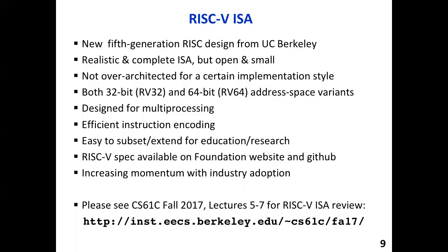In fact, if we wanted something like RISC-V, not only would we find the full-blown VHDL available, which is cool, but we'd even find compilers that support it, which is really important if you want to start writing programs in C and having them actually compile to this RISC-V processor. Because once you got that, now you can bootstrap the cross compilation of a whole operating system that's going to run on your little FPGA.